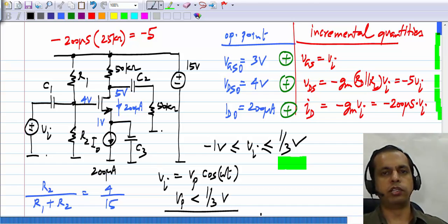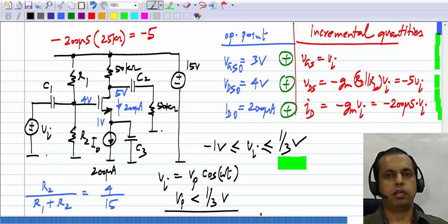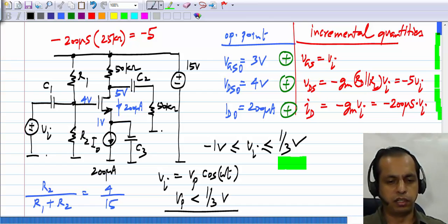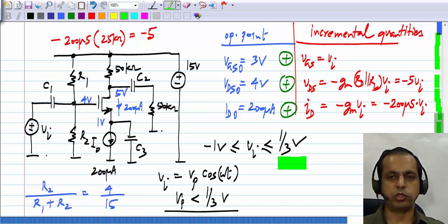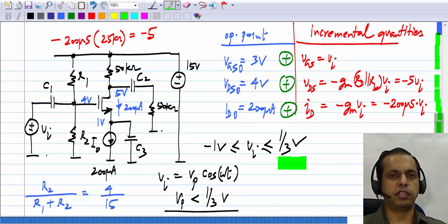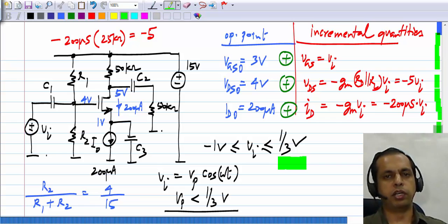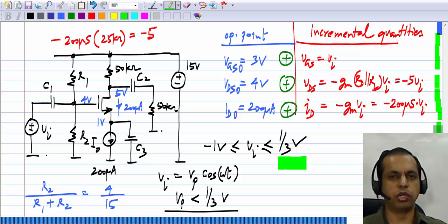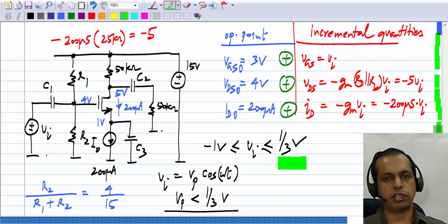What we do is calculate the total quantities everywhere, that is VDS, VGS and the drain current ID, and we impose the limits of going into saturation or cutoff. And in case of the cutoff limit, there are two possibilities: to either set the drain current to 0 or the gate source voltage to 0. In our case, we will uniformly use the limit imposed by the drain current. We know that it's only approximate, but we are first of all looking only for a crude estimate, and we also want to use the same method for MOS transistor circuits and bipolar transistor circuits.